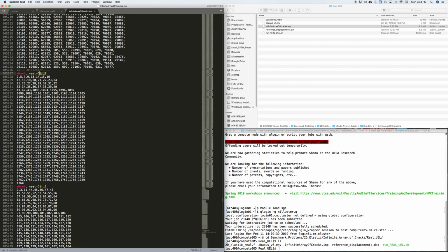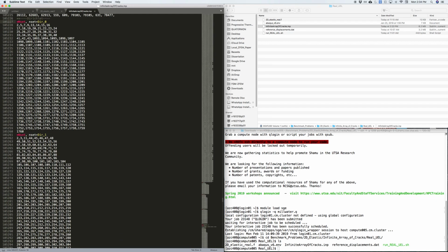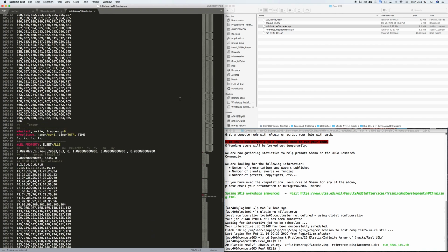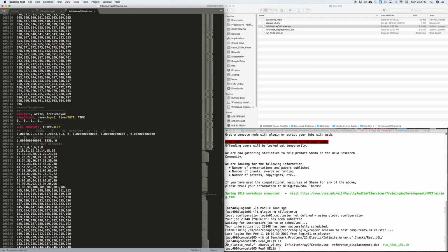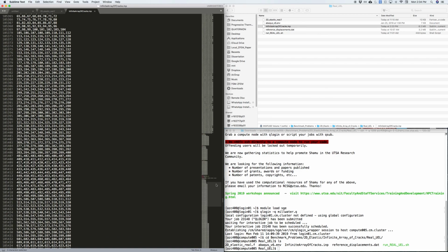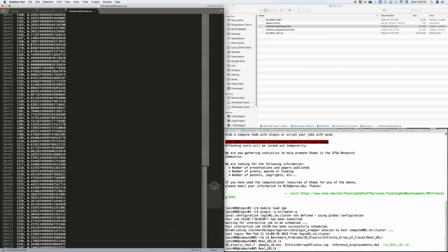This is going to be dir1, which stands for Dirichlet 0. Then we have a Dirichlet 1, and then we have a node set called dir2. Those are associated with the boundary conditions that we are going to show later. Then we have the UEL properties, and for the purpose of this example, we are going to care about these 2 properties, which are the elastic modulus and the Poisson ratio. All the other properties are not important for this simulation.